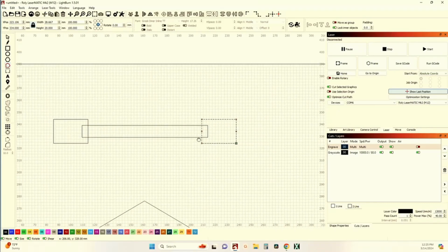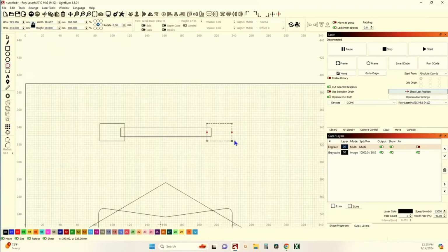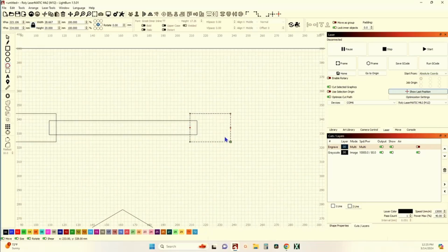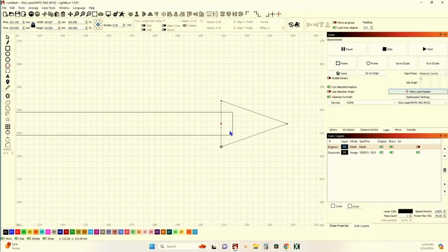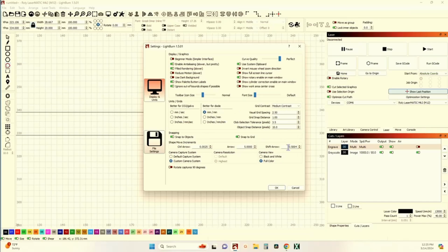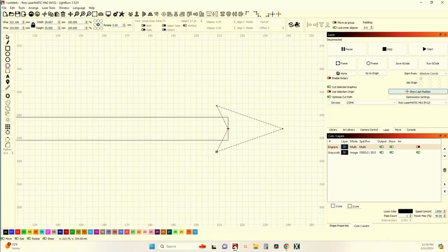And now I will select both of these. Actually, you know what? The first thing I need to do is select this one and hit the letter D. Letter D. And now just simply hold my, see how where my movements are. With the shift arrow, I need to be moving, let's do 2.5 millimeters. Let's say okay. So 1, 2, actually just 5 would have worked. That took it right back up there.